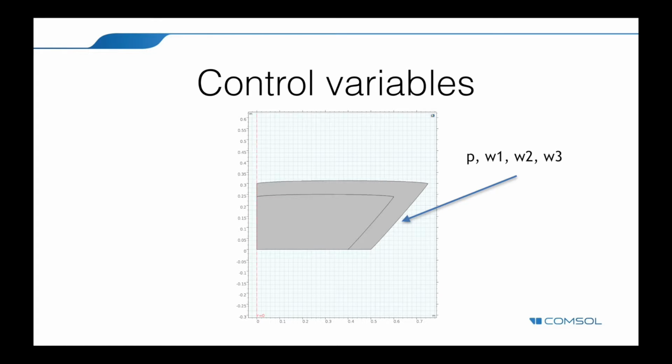Control variables as geometric parameters are included. Those would be easy to change when developing a design parameterized by the position P and the weights W1, 2, 3. We added logical bounds to the variables, ensuring that any two geometric control points will not coincide, as this will cause a program error. Only the selected variables can be changed during the optimization study, but they do not all have to be.